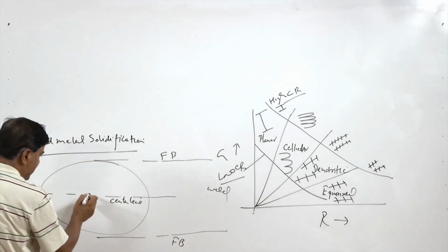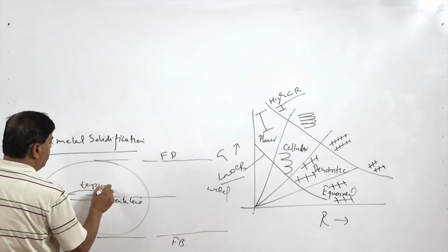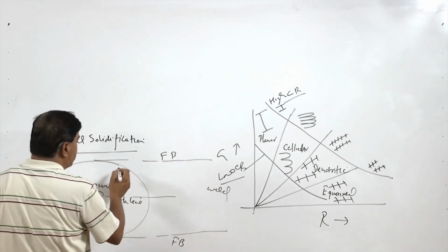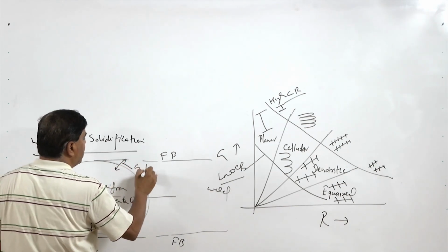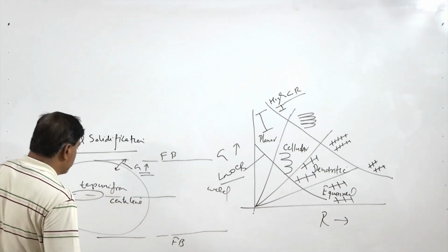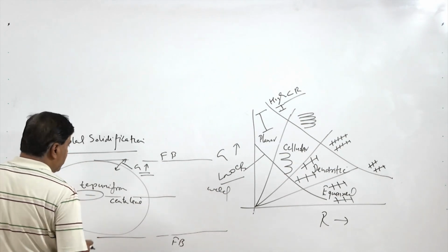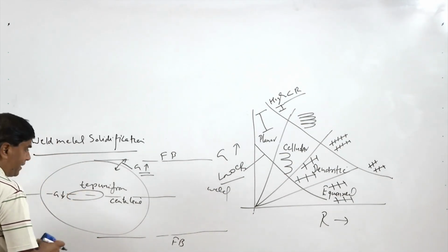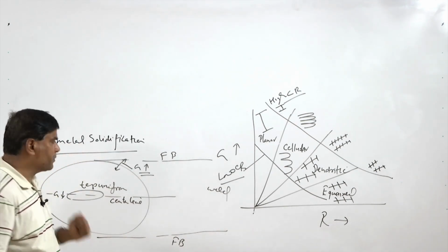At the center line of the weld, the temperature is uniform, although it is at its peak, while at the fusion boundary there is a sharp temperature gradient. So G is actually high at the fusion boundary, while G is low at the center because of the uniformity in temperature. So G value is low at the center, while G value is high at the fusion boundary.